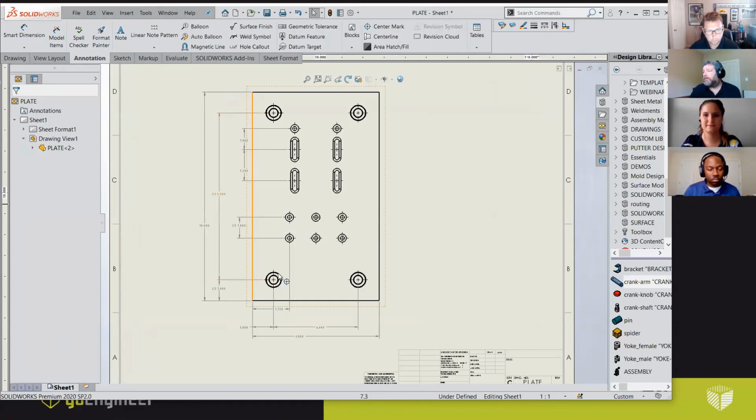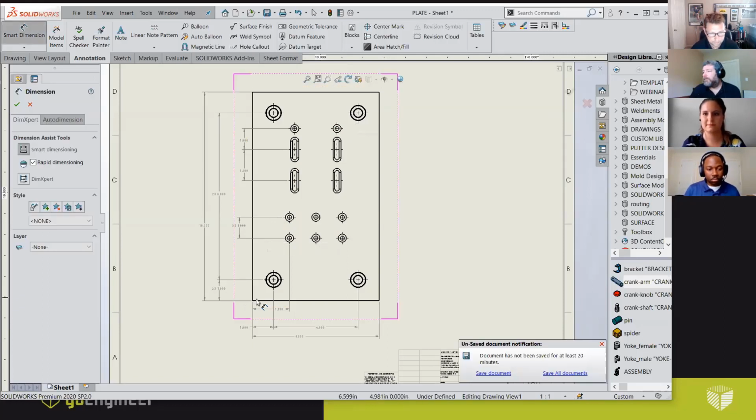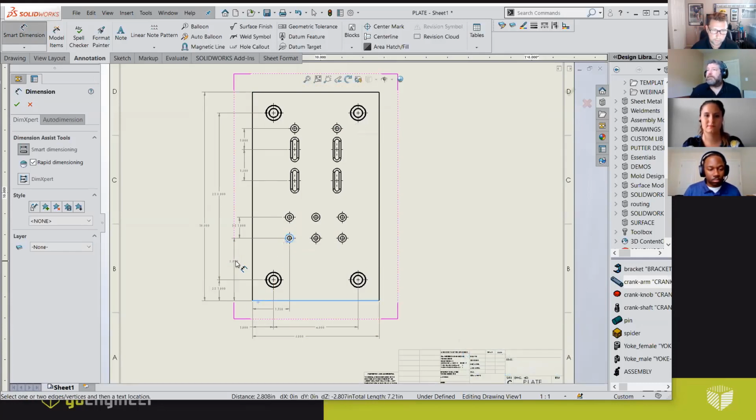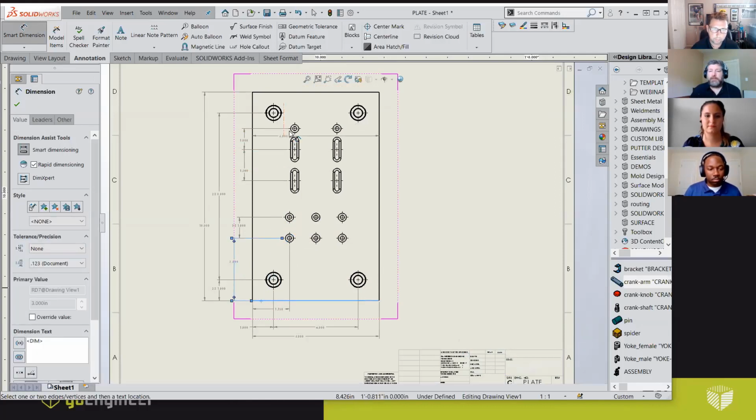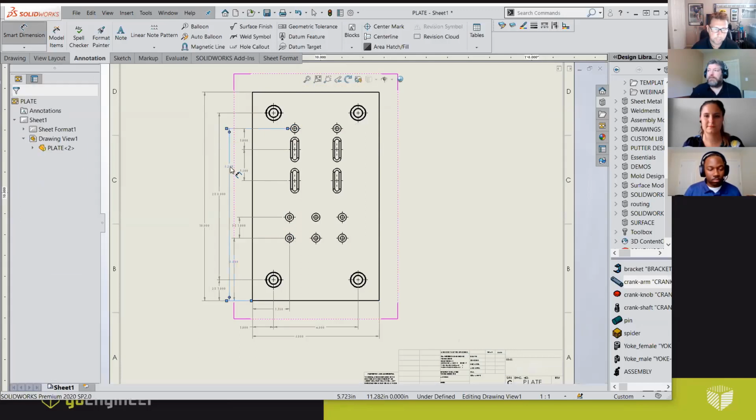But we've got this plate that has one hole pattern, a second hole pattern, and a third hole pattern. To put all these dimensions on here, what can happen occasionally is this drawing starts to get messy. So let's say that this is our 0, 0 point for now. I'm going to pick this edge, and pick this dimension. I want to stick this dimension over here on the left side. Then I'm going to go back from here to here, and I'm going to locate this first hole because our hole pattern is pulling off of there, right?